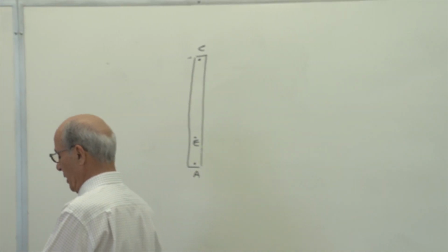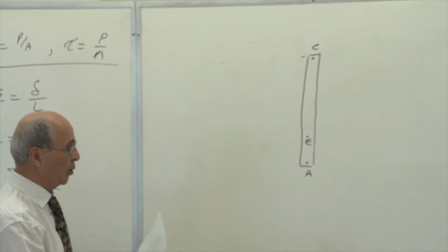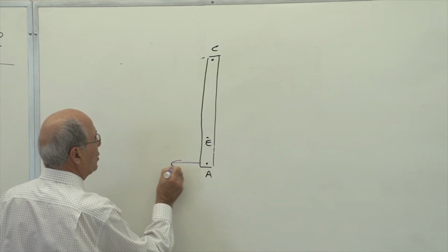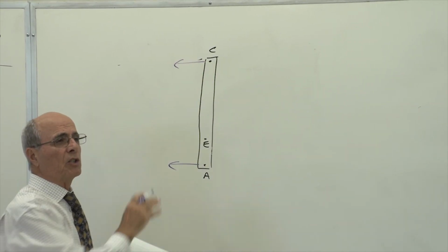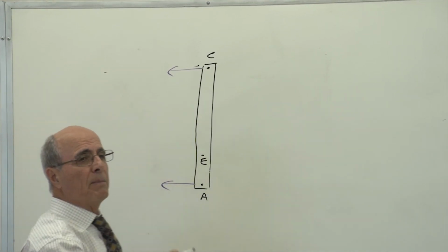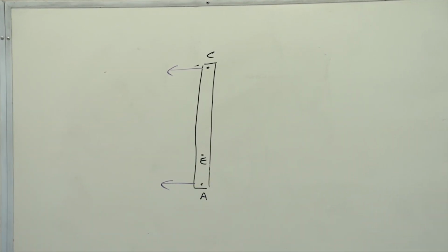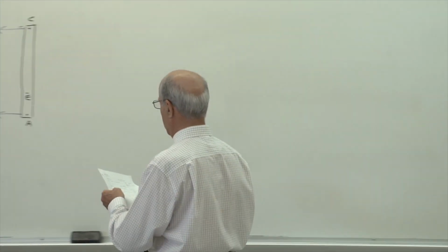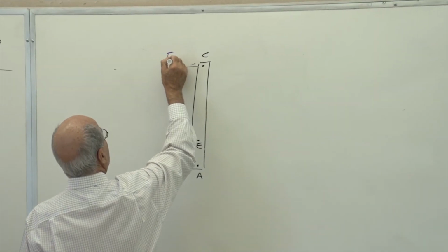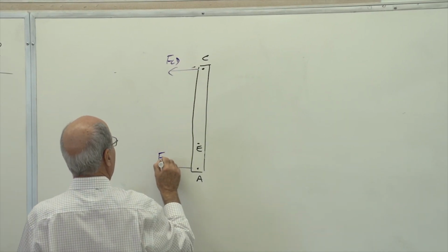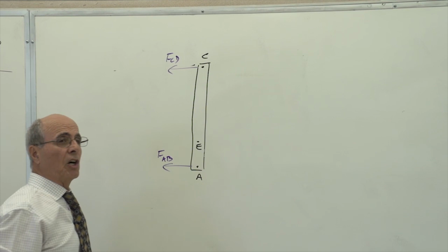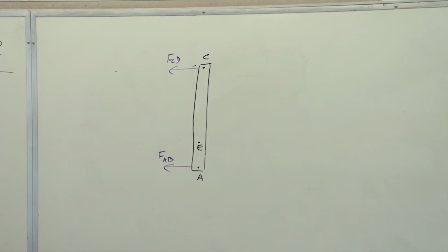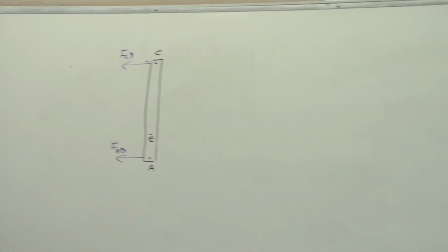Back to your quiz or your homework, the previous homework. When you draw this free body diagram, there must be a force here, there must be a force here, because those are two-force members. You have to draw the forces in the direction of the member. Therefore, I have a force FCD, and here I have FAB. These are drawn, not statically, they are negative, but they are drawn, again, I explained that at the beginning of this lecture today.